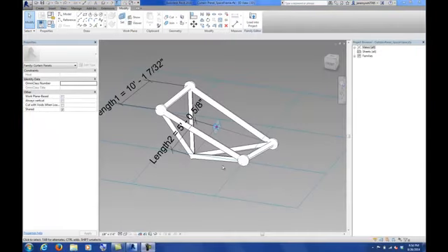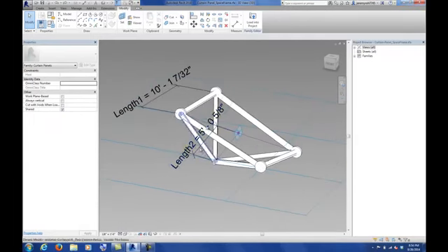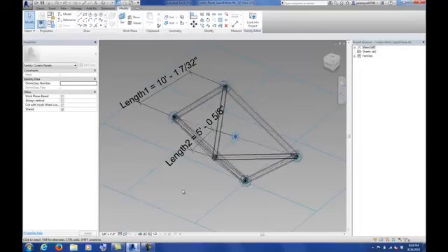At the end of class, I just want to do a quick follow-up here. I couldn't get the length 2 to work out as a reporting parameter. One of the things I did mention in class, but want to reiterate, and that I didn't follow, is Revit's rule that anytime we do reporting parameters, they can only be hosted to elements of the family template.